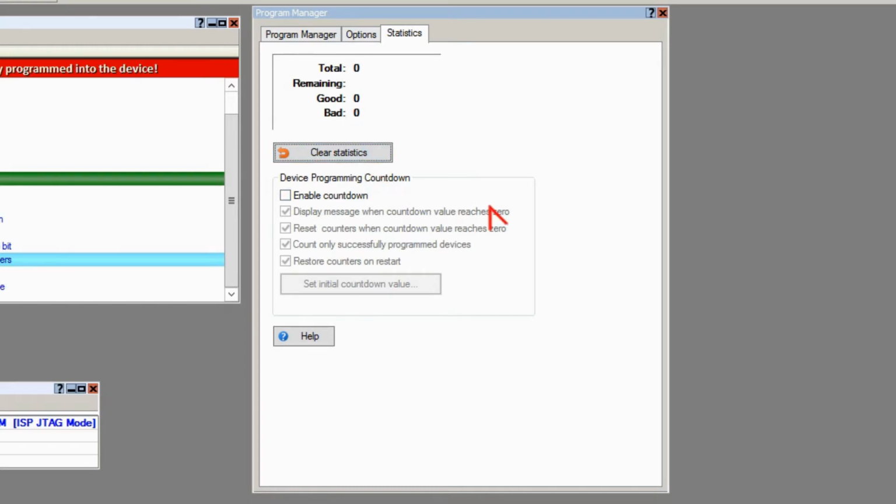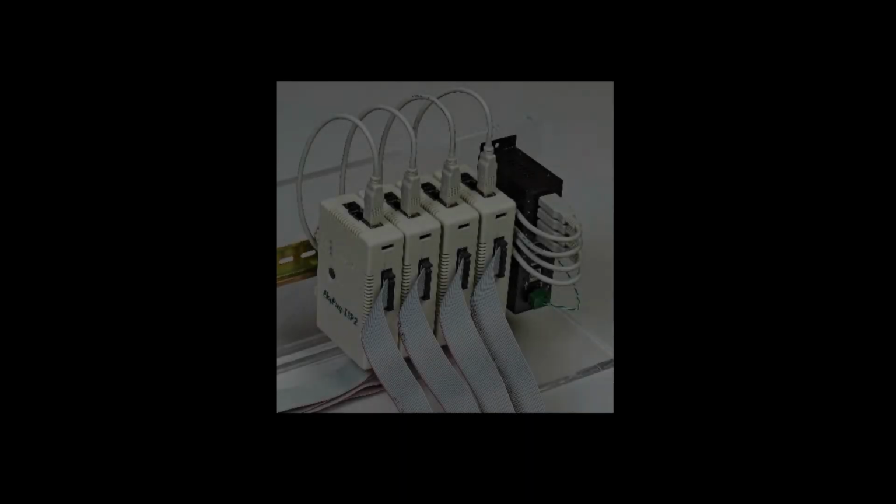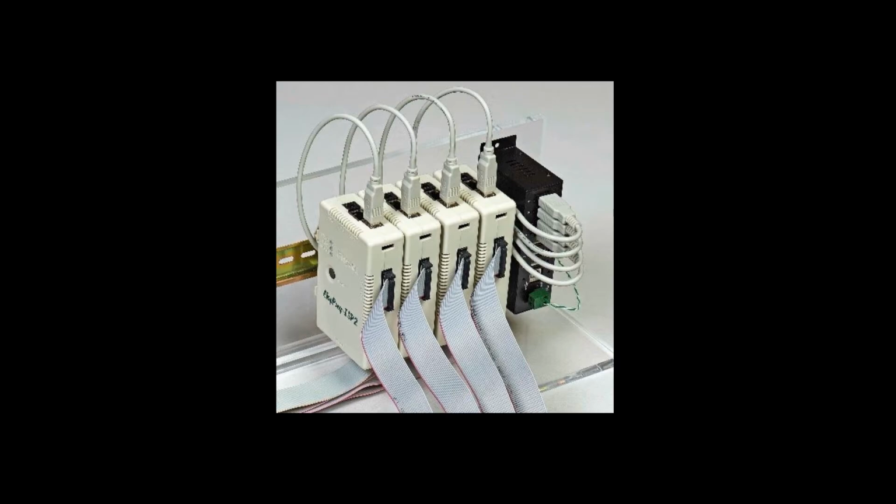Now, after reviewing the GUI for a single CPI2-B1 programmer, let's talk about use of multiple CPI2-B1 programmers for flashing multi-PCB panels in mass production. A virtually unlimited number of CPI2-B1 programmers can be controlled from one computer in the gang mode, flashing multiple devices in parallel. The picture here displays a cluster of 4 CPI2-B1 programmers mounted on a DIN rail.